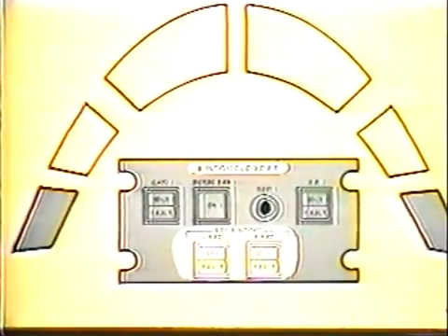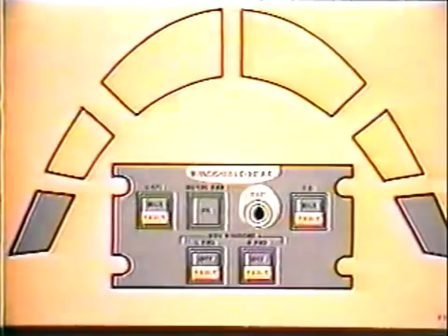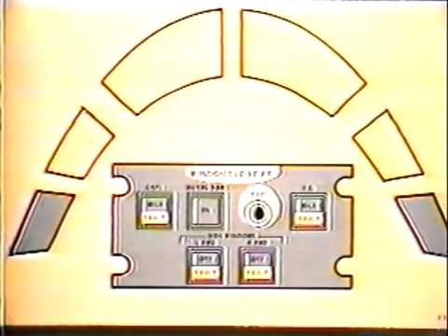The side windows operate at one temperature. Normally, the switches are latched and dark. Fault lights indicate a malfunction of the windshield heat system. Pressing the windshield heat test button will cause the four fault lights to cycle rapidly during a normal test. A failure to cycle indicates a malfunction. The captain and first officer switches may be latched or unlatched, but the side window switches must be latched for testing.